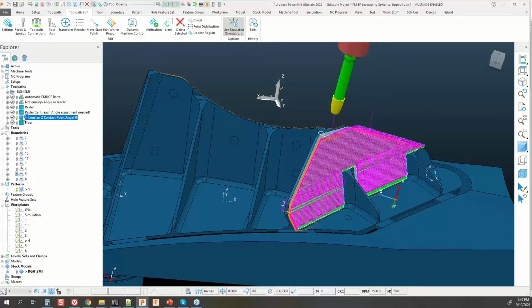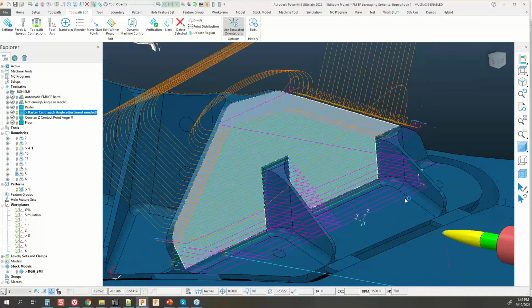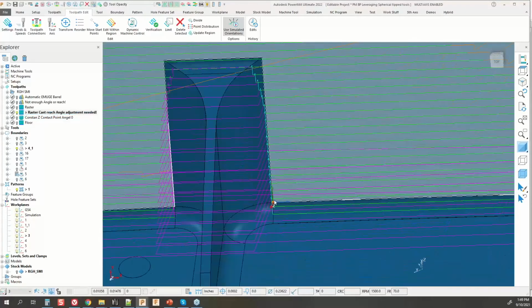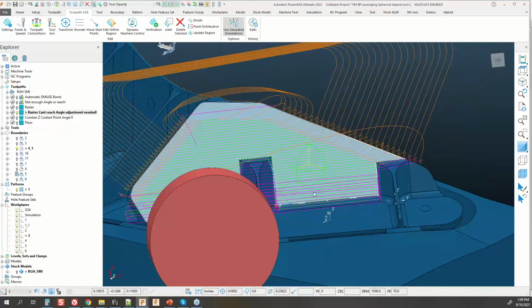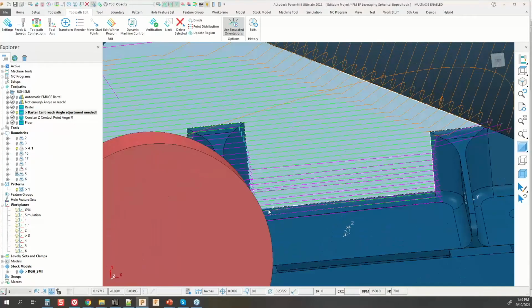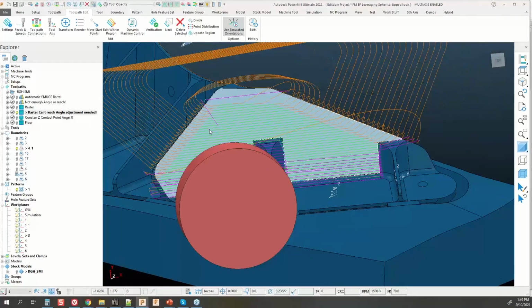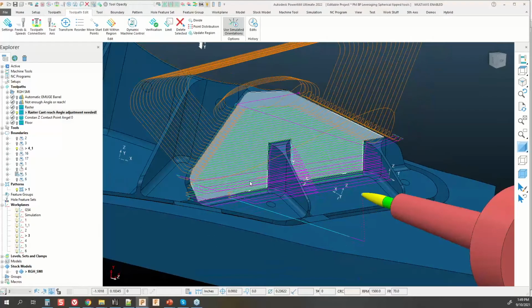Or I mean the constant Z toolpath for this one. So I rastered that one, and based off of my raster, I also set my work plane along that surface, and I also clocked the X and the Y pointing in the direction of the surface so that I can get the raster angle correctly to it as I calculated these toolpaths, right, for that angle.